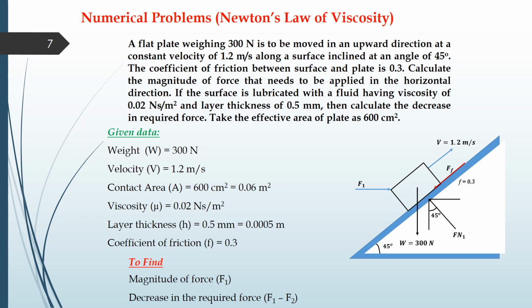How will we move? What we will do, by using the basic mechanics principle, we will use a summation principle wherein the summation of the forces in x direction will be equal to 0, and the summation of the forces in y direction will also be equal to 0. Okay, so we will resolve this Fn1, and it has been resolved over here. We will resolve in this plane over here. This will be taken as x and this will be taken as y.